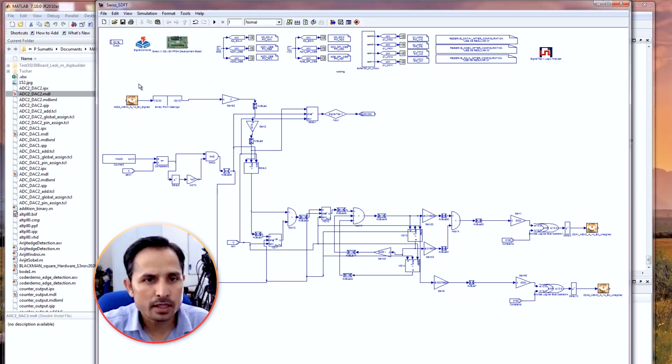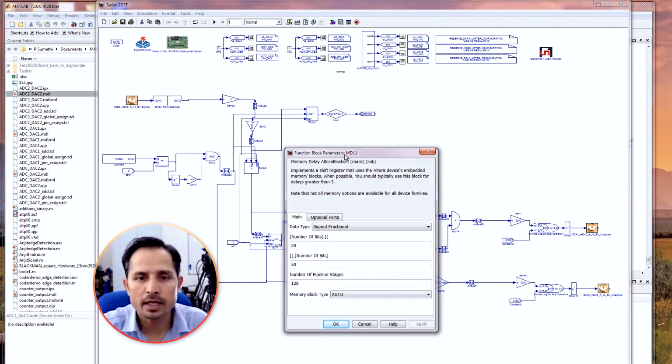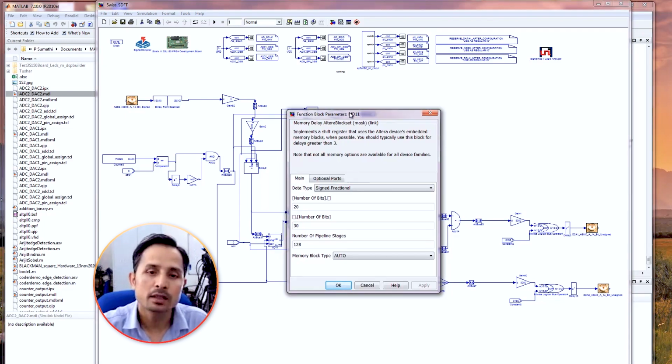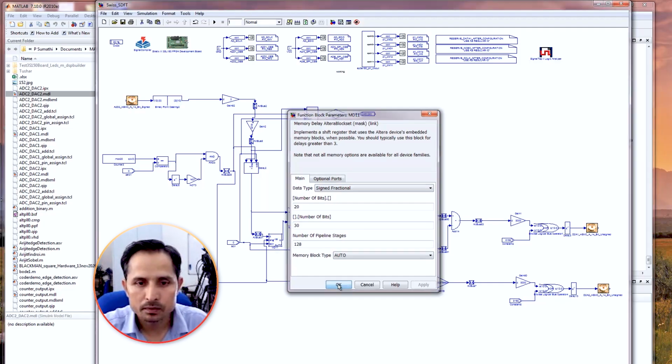So the signal is first passed through this delay to register the signals, and this part is the comb filter. So this is the first x[n] minus x[n minus m]. So this is like x[n minus N]. So the N-point basically SDFT. So N is taken here as 128.